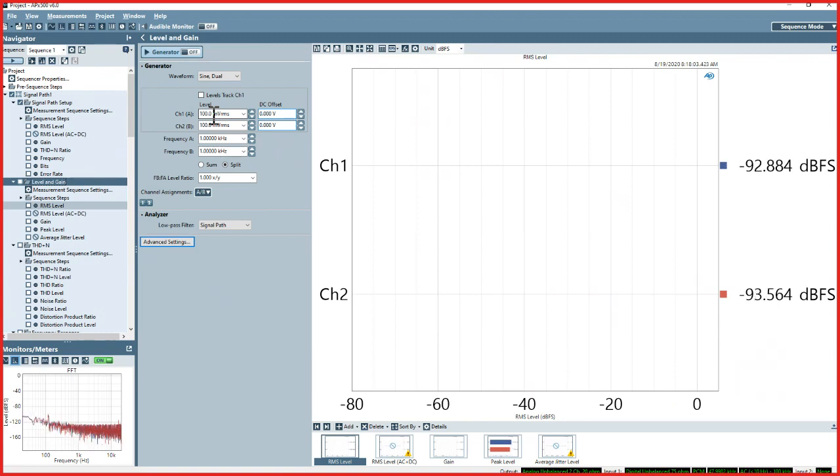So what I'll say is in most serial interfaces, not in all serial interfaces, they're what we would call source synchronous. That is to say, all the clocks are going in the same direction. So for example, in the device I'm testing today, the APX is the source of the master clock, the bit clock, and the frame clock.